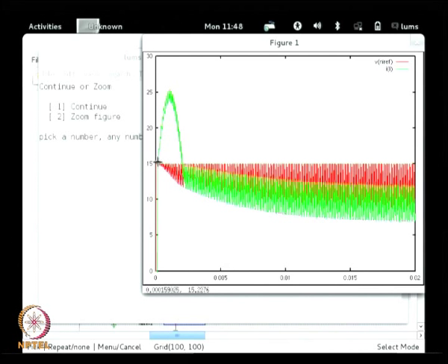So, the inductor current will rise for the 10% time, then fall, and so on, keeps rising till it overcomes the transients and then starts going to the steady state. This can also be controlled by giving a soft start or decreasing the clock duty ratio to much smaller, like 1%, because it is only the positive edge that is needed to trigger the SR flip flop.